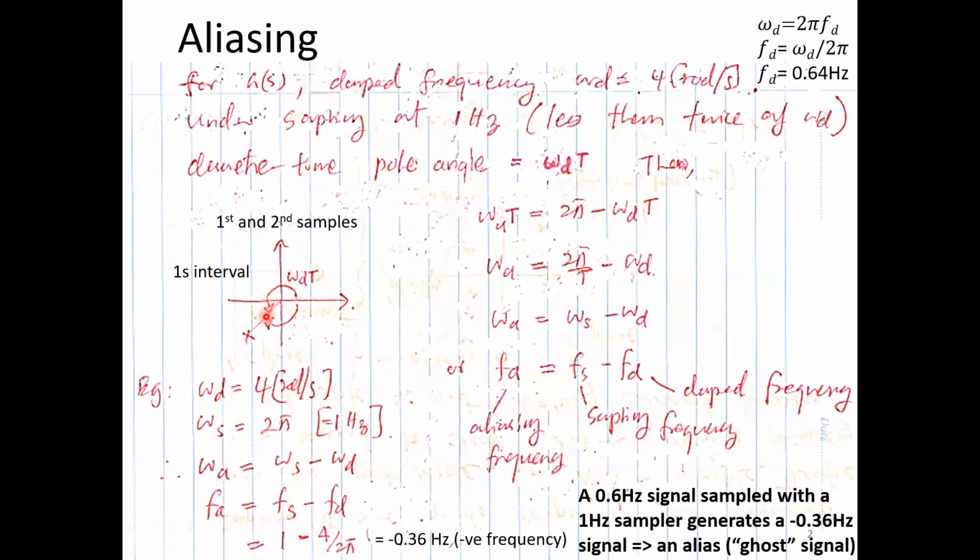If you collect the samples like that and produce them to someone else, and he doesn't know that you have violated this fundamental law, Nyquist's law, he just looks at your samples and thinks that you have gone not this way but that way. You can go to the same point in two directions, anticlockwise or clockwise. Usually we go anticlockwise, the positive direction. Everybody thinks when you produce a set of samples, these samples are taken anticlockwise, in the positive sense. But here it is not the case. You are taking samples in the opposite direction.